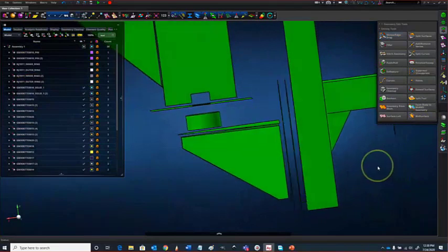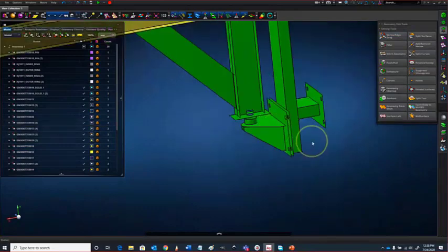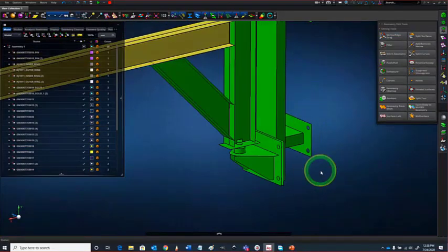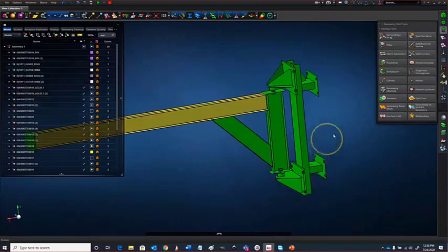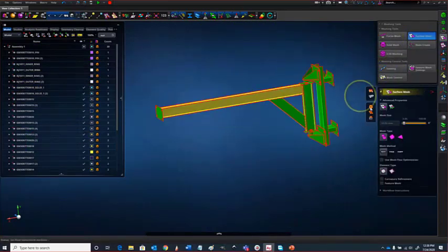I'll leave all these bodies physically unattached, but we're going to attach them using glue. We actually get better results that way in any case, so I'll be demonstrating that as well. And now we can mid-surface all of these bodies in one go.